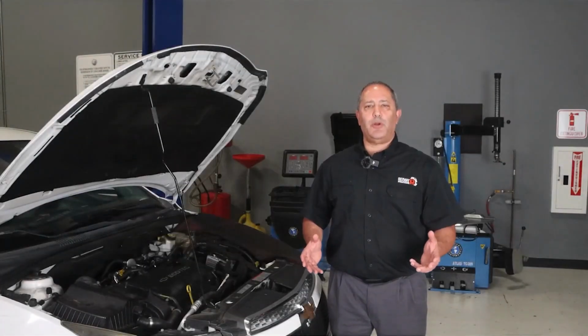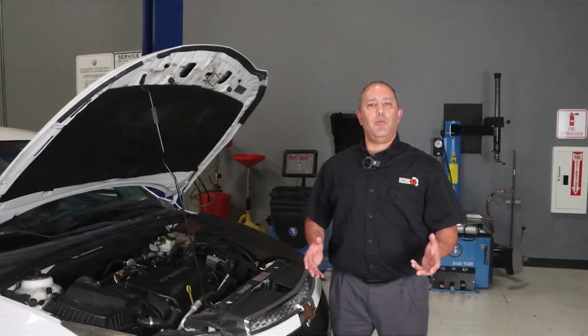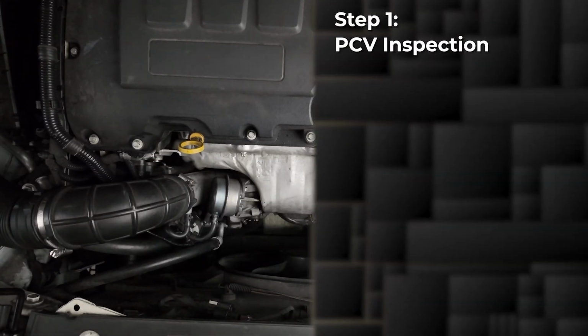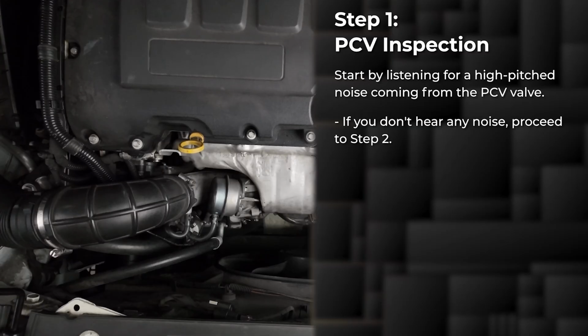If any other trouble codes are stored, diagnose and repair those first. Do not continue troubleshooting this code until all related faults have been corrected. Step 1. PCV inspection. Start by listening for a high-pitched noise coming from the PCV valve. If you don't hear any noise, proceed to Step 2.